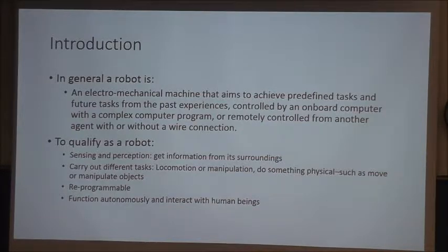If you're working on underwater robotics, you should have a wire connection, because you have to supply power and meanwhile communicate with the robot. Or if you're working on a Land Rover, the communication should be wireless, and you have to deal with your power source.